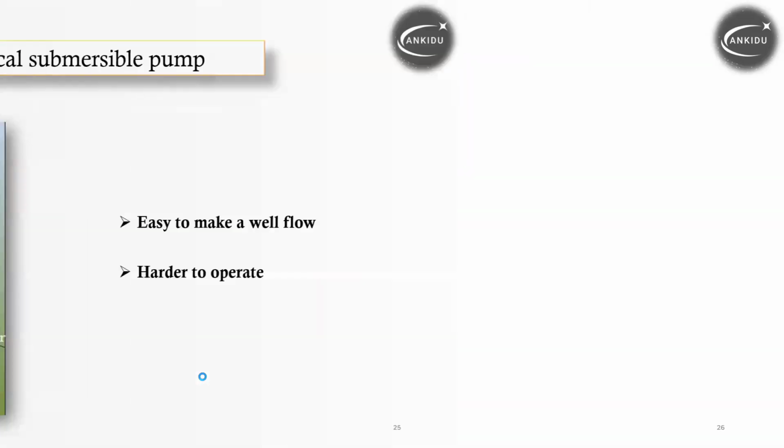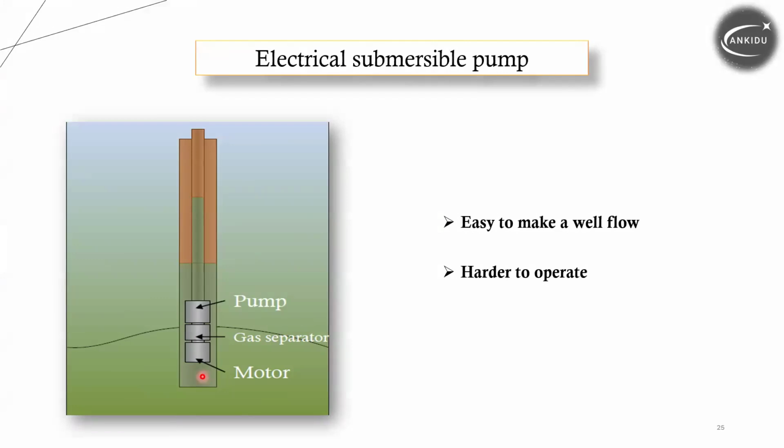But sometimes it's harder to operate. Why? Because you have to consider the pump condition, whether you have any high hydrostatic pressure, water cut, or gas breakthrough. You have to consider whether it is worth operating the well again without causing any damage to the ESP or not. So what are the well parameters in terms of the PVT before running the ESP and losing that ESP?